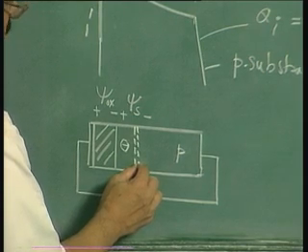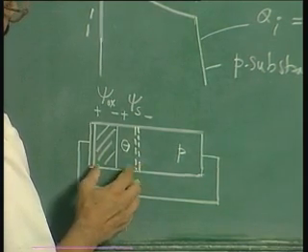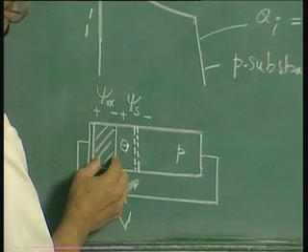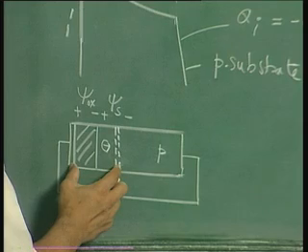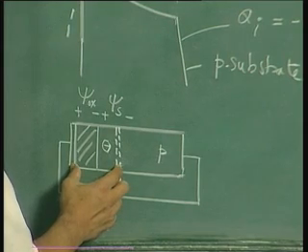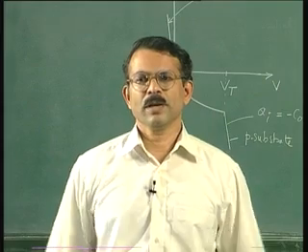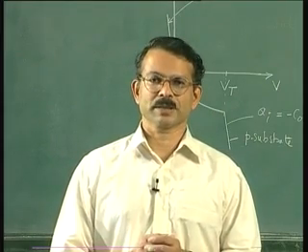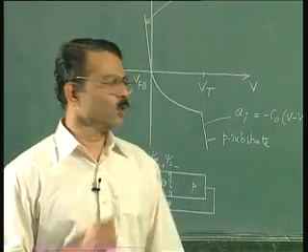So here evidently the capacitance is smaller than the oxide capacitance, because this is the distance between the changes in the charge. That is the incremental picture. Now let us draw the incremental charge picture for an increment in the voltage.